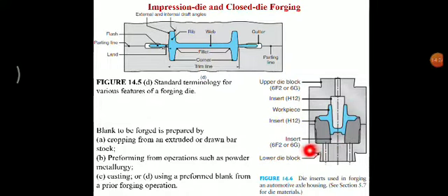This will be the lower die and this will be the upper die. Now this will be the upper die insert and this the lower die insert. Both are made of H12 material. And this blue colored part is the workpiece material. You don't find any open space like a gutter here. And here the pins are provided for ejection of this component.